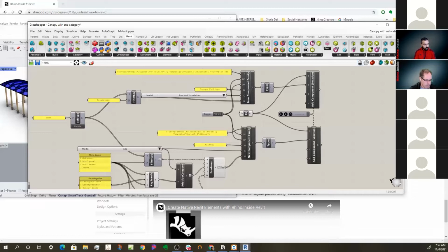There's something called packing. When we go from SubD to NURBS, we pack the patches together into larger patches, so there are fewer patches. That really helps a lot with using SubD. In Rhino, it'll be a SubD; in Revit, it'll be a NURBS. When you change the SubD in Rhino, it'll translate into NURBS and into Revit. So that should work fine, and that's a good, accurate conversion.